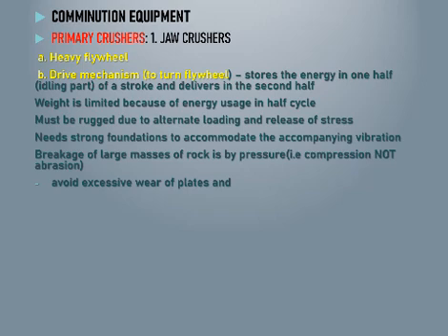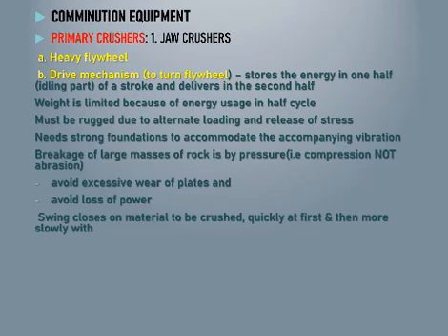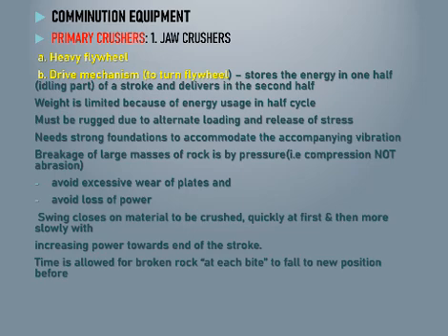Breakage of large masses of rock is by pressure, that is, compression, not abrasion. Avoid excessive wear of plates and avoid loss of power. The swing closes on the material to be crushed, quickly at first and then more slowly with increasing power towards the end of the stroke. Time is allowed for the broken rock at each bite to fall to a new position before being nipped again and another stroke cycle ensues.